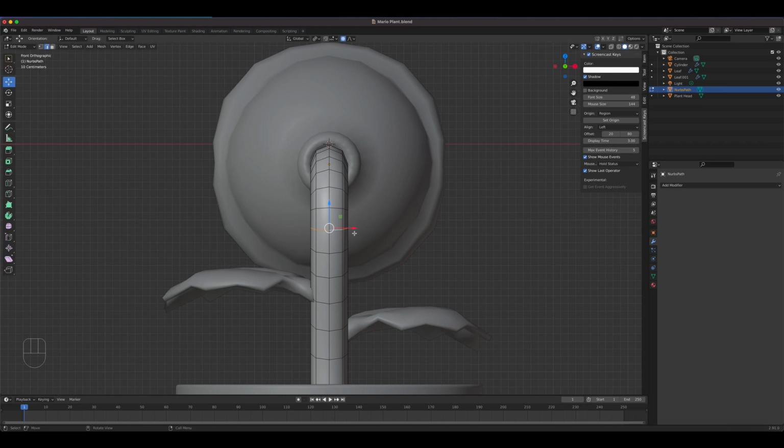So I want to use a move tool, G. Okay, so I'm going to press G. When I do that, I get a reticle, so I can scroll my mouse to reduce or increase the area of influence. And you can do this in real time. So right now I have G pressed, right? I mean, clicked. So if I move this, you can see it affects the area, not just that selection. But watch this, when I scroll my mouse, it grows the selection. So it's actually very interactive.